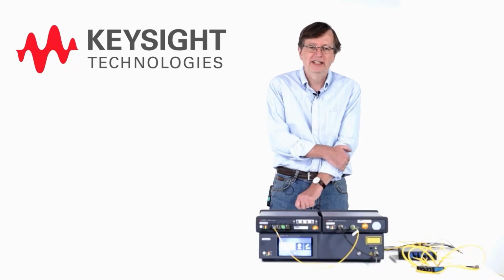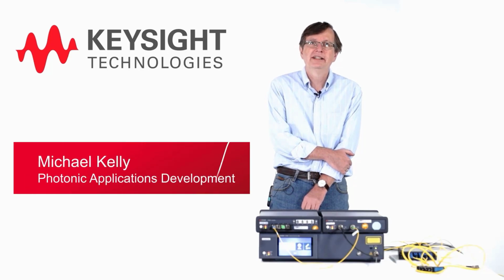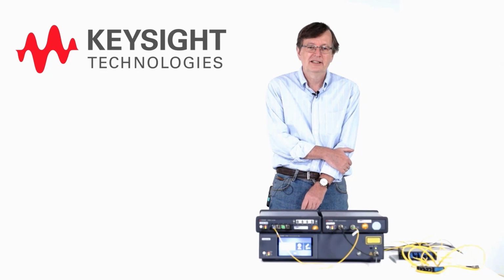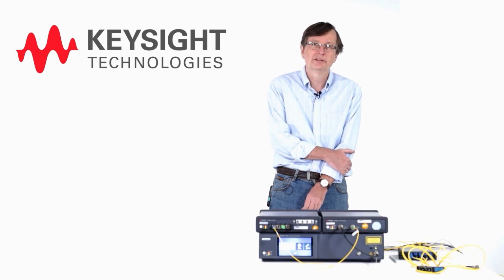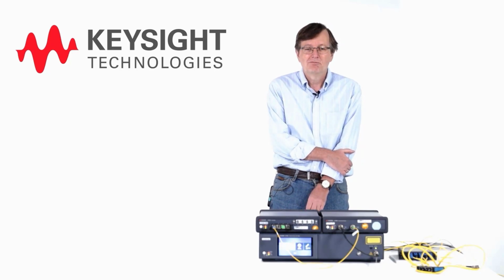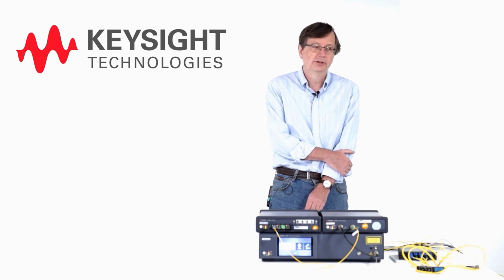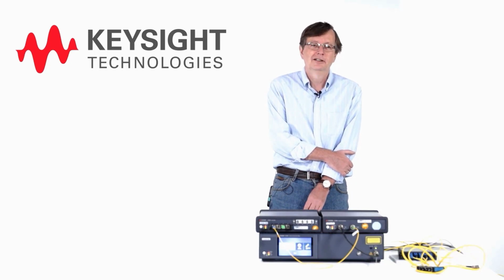Here we want to demonstrate our system for measuring insertion loss and polarization dependent loss, or a dependence of wavelength and polarization for optical components that we test in the networks. And this is one of the basic and fundamental measurements that are made now also for photonic integrated circuits, wafer level or chip level measurements. And so we want to go into those details because we've got new instruments and software that really support this function.